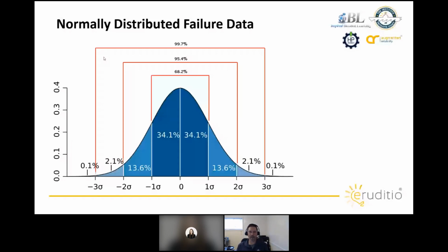We want to be able to detect throughout that entire PF interval and have a good confidence that we're going to catch it, right? That's why once we start to acquire data on these failures and we start to have operating context specific failure data for the specific failure modes, we can use various statistical analysis tools to refine that a bit more, right? But in my experience, most organizations don't have that data, so we have to rely on 6-to-1 rules and subject matter expertise when establishing these intervals.